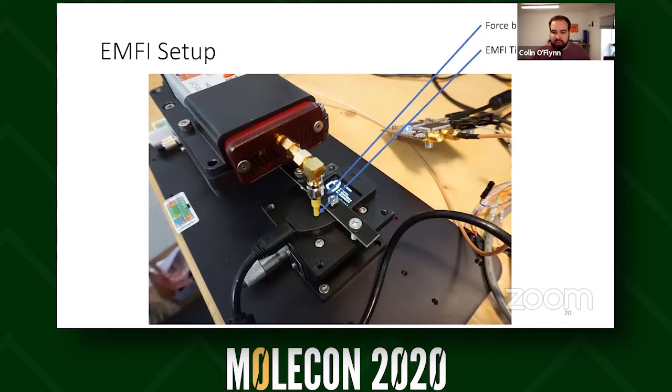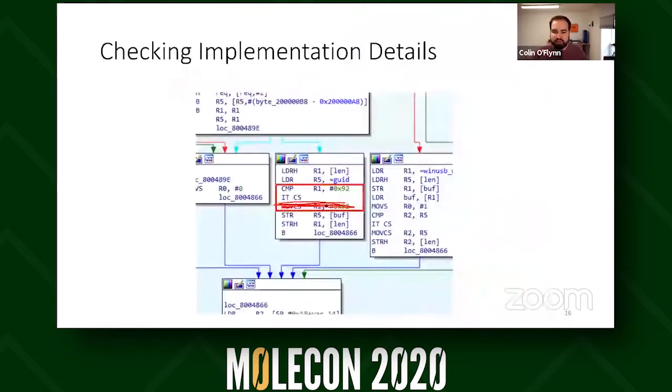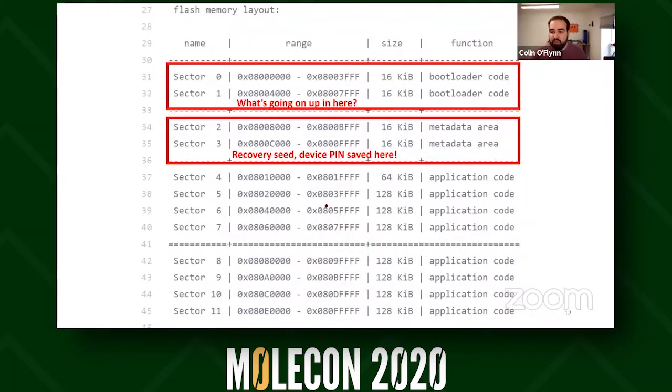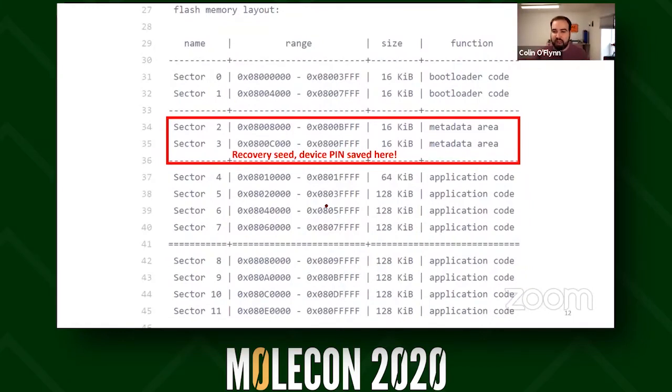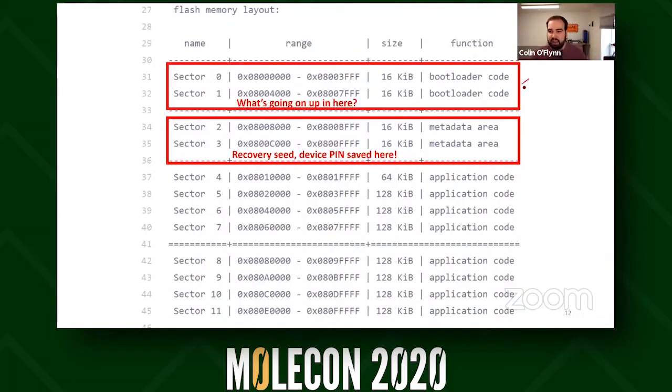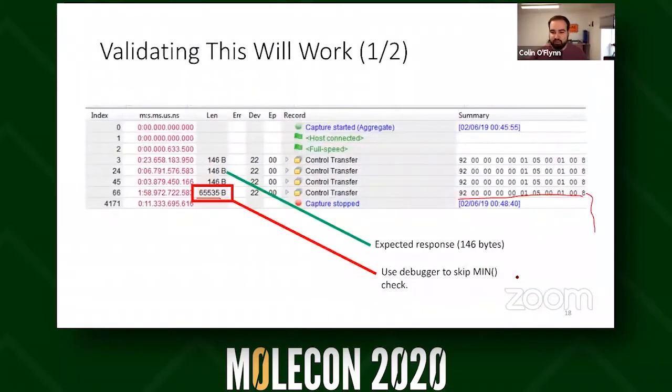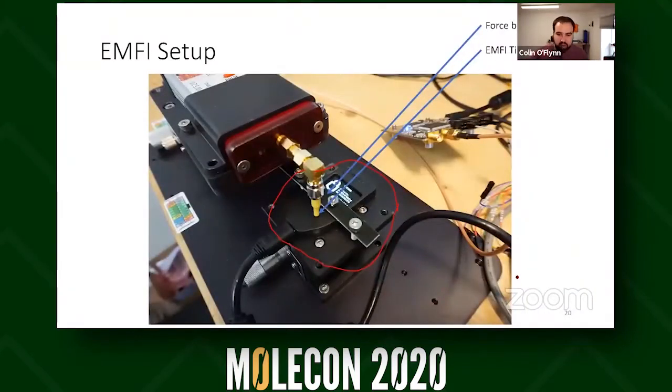You can see this sort of holder here has a bootloader force. If you hold down the two buttons, it always goes into bootloader mode. And we want bootloader mode because, if you remember back here, only the bootloader code right there has the USB stack ahead of the data, because we're going to start at something and just read past it. If you try to run from the application code, it's less interesting because it's just going to read further into the application code. So that's the reason we do the bootloader mode.